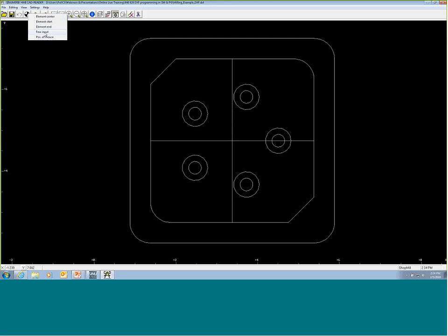You can do a free input, so that would give you an actual scale to be able to type values into. Or I can give it the position of the mouse. If I give it the position of the mouse, I could roughly eyeball some arbitrary location and establish that to be a 0. Generally, that's probably not the most ideal way because I'm not truly controlling the 0. So normally, I would pick an element center. Here I could say, I'm going to pick this line, or I'm going to pick a circle or a feature, and it'll find the middle of it.